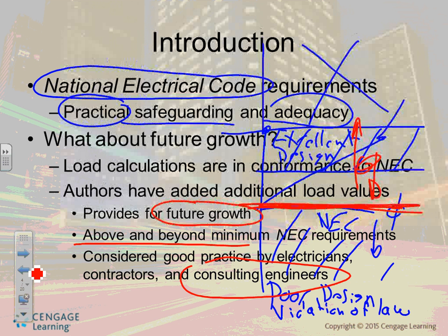So a couple of examples, guys. If you don't tell the contractors how to circuit, how many receptacles in a circuit, well, guess what? They're going to follow the law. Where was the law? 10 receptacles per circuit. That's cheaper for them to do, right? You didn't tell me how to circuit, and I met the code. I met the law. That's where we push the envelope, and I'm bidding it, so I need to make money. So there's an interest group. Please be aware of that one.